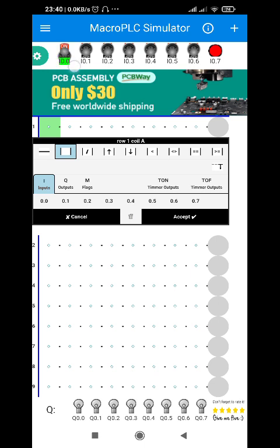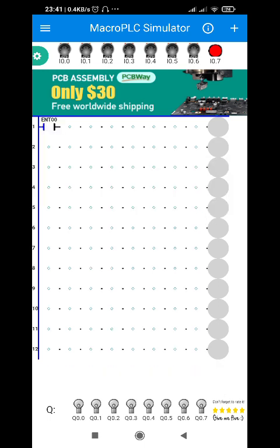So if you notice, we have I0.0 located at the lower part after the toggle switch. We see the I0.0. So that is the address that we are going to use. So I selected I, and then I choose 0.0. So we have I0.0 and press accept. Again, I said before that the ENT00 is designated for our first toggle switch, so that is the address for that. So when I toggle the switch, we see that it is highlighted.